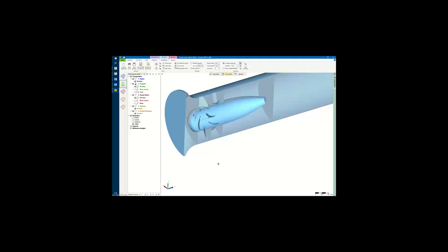In the end, I think a user has some preferences. What we learned is that CFX is a bit more robust when it comes to compressible flow, especially, right? But to answer the question, yes, CFturbo works with Fluent, because in the end it's only a matter of which solver you choose in Ansys Workbench, and that's it, right?